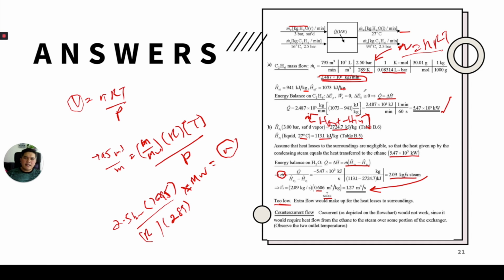So what type of heat exchanger should be used? Usually in this particular system, as you will learn later in process heat transfer, it is of counter current flow. What does counter current flow mean? Right now, what you can see is an arrangement of co-current flow. Counter current flow is where this particular stream is somewhere around here and the arrow is going in this direction, and this one is at here, or the other way around to the top. So that is counter current flow.